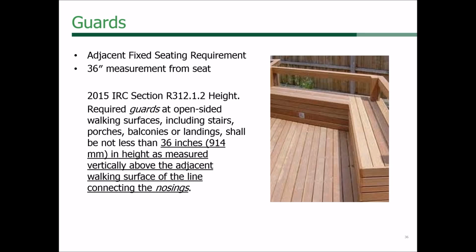Now, not all decks require guards. Only decks that are 30 inches above adjacent grade are going to need them, and it's going to be up to the building official. I've heard it both ways as to whether, if you have like a 20-inch deck but you do guards, they need to have the same level of safety as a guard that was 40 inches off the ground.